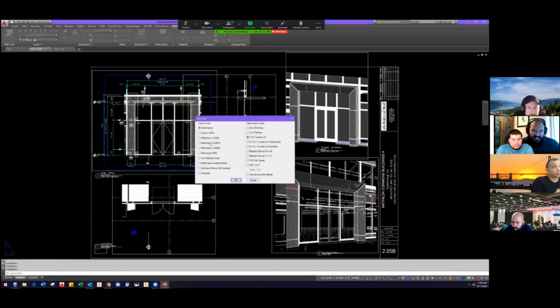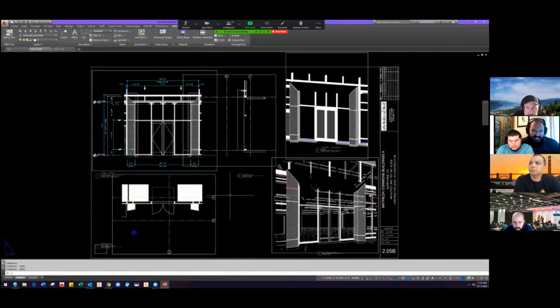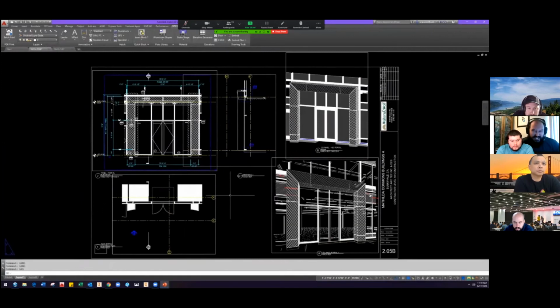And then once we create the sheets, we would place mark numbers, make sure it's on the right tag, so when we print, you could see it from the tag layer that we used for panel mark numbers, which was the LMM1 function in AutoCAD. And so it left a lot of room for error if you were to place mark numbers and forget to change them into tag 3 layers.